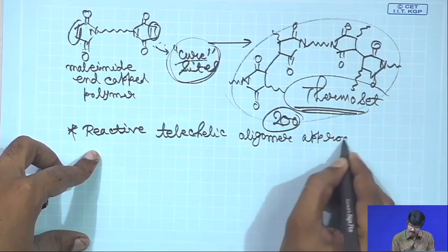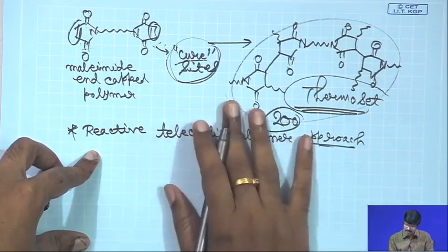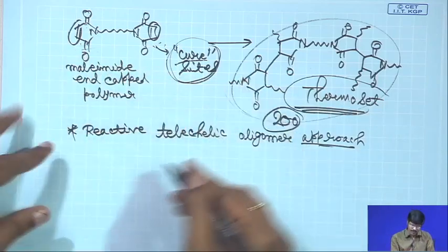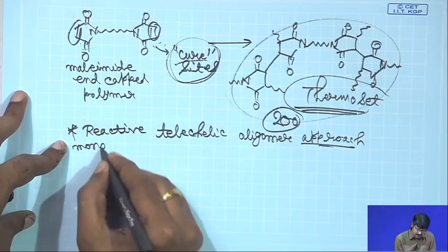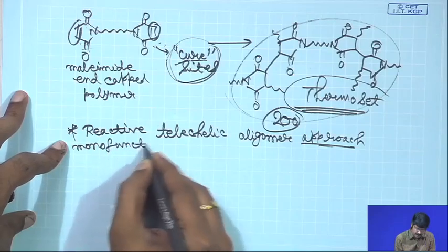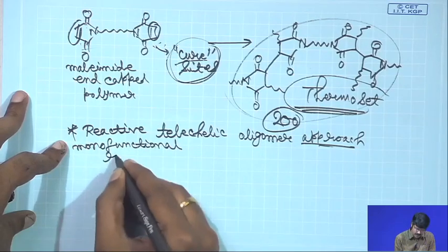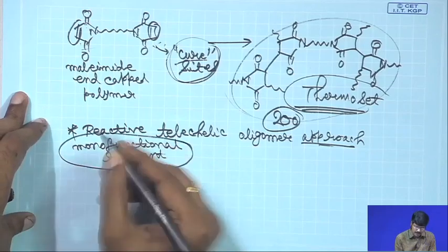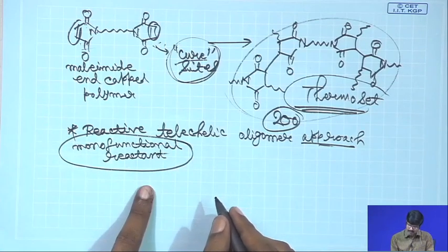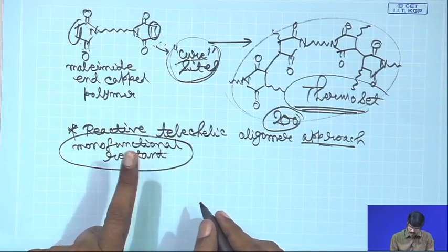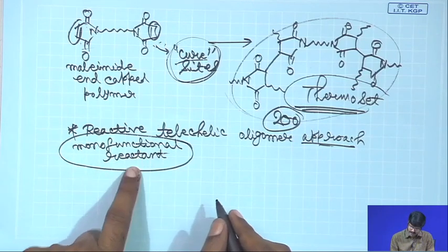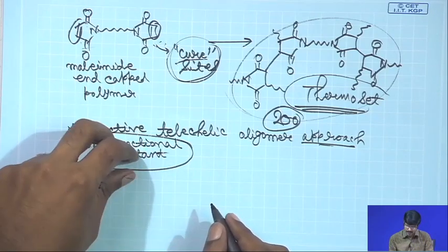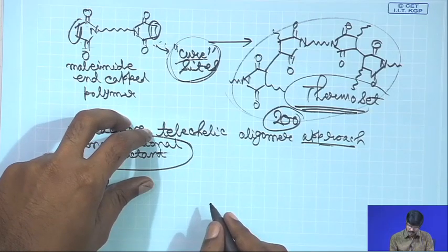approach. So, in this approach, what you basically do is that when you are polymerizing your system, you include a monofunctional reactant in the system. So, you basically add a monofunctional reactant. Of course, this will end cap because it is monofunctional, and this is how you can also control the molecular weight. We talked about that before. So, this will limit the polymerization, and secondly, it will end cap the oligomers with functional groups that are capable of further reaction. All right.